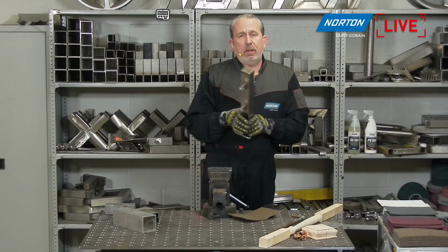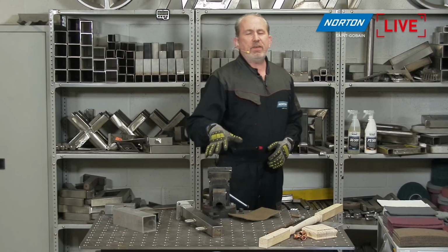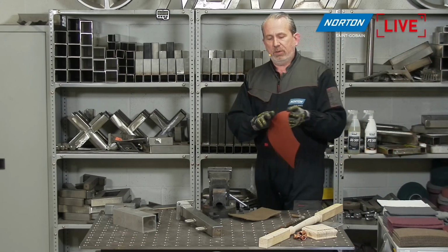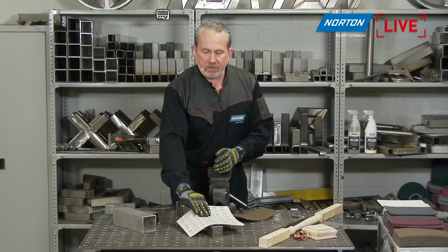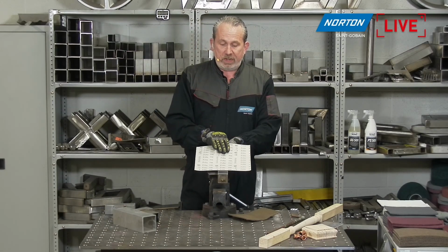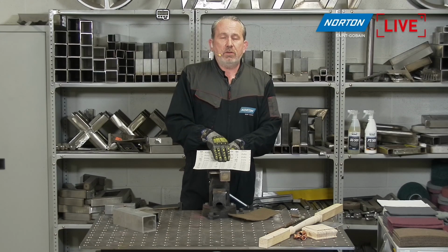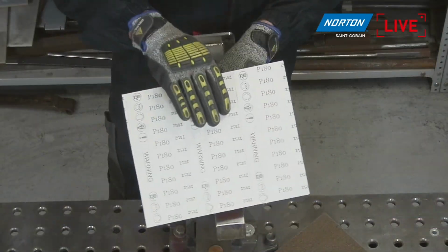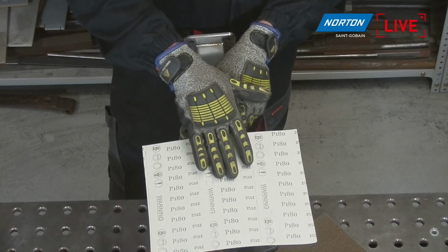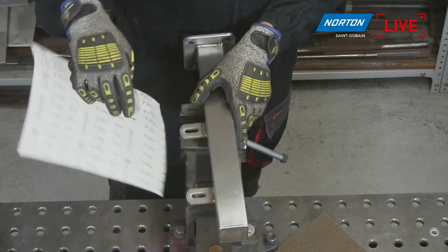Another thing where hand pads benefit on more aggressive applications like this is when you're using sandpaper, you're pushing on it with your fingers into something like here. So you actually get more pressure into where you're sanding with where your fingers are touching. So you'll actually see that in the surface finish that you get with these two fingers when you're trying to sand on there. You'll see more aggression on the material.